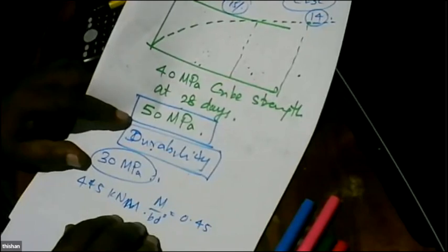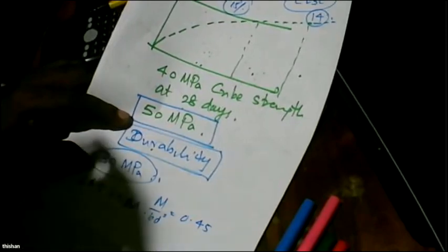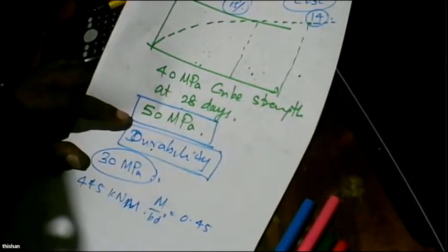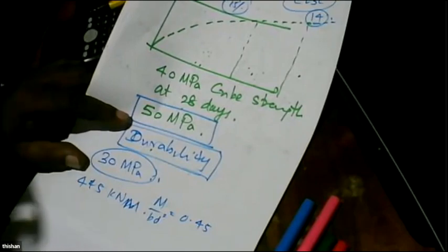So concrete is going to be high-strength concrete, like 50 megapascal or more with time, and we are going to use 500 megapascal reinforcement, but minimum amount of reinforcement, minimum amount of concrete, and doing so, a very lightweight bridge, but strong enough to carry HA and even HB 25 units of loading. And if you want a little higher loading, like 180 kilonewton HB loading, you might need a little more reinforcement. So with that, I can come to the end, and if you have any questions, I can answer.